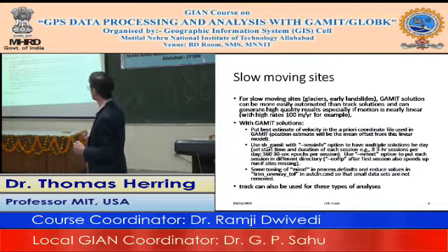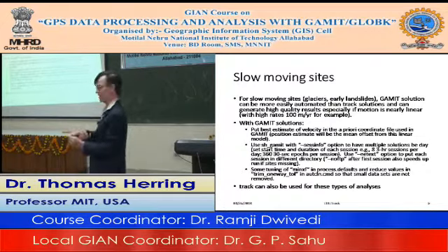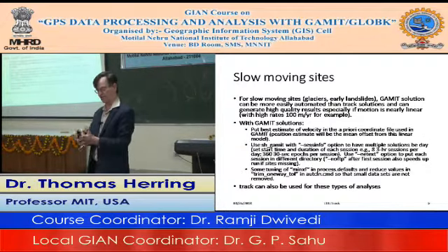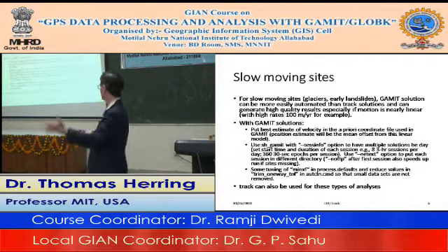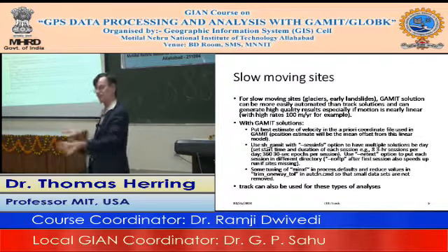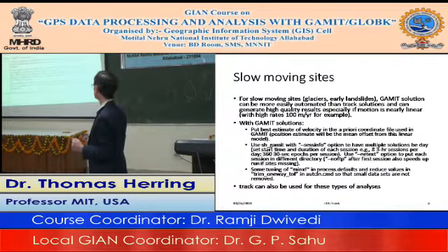So when you do it in sh_gamit, I was talking to some people about this, there's the -sessinfo option. That allows you to specify when the session starts and how long it is. So it's very easy then to batch up data to process, say, 6 sessions per day, each 4 hours long, and you just do the successive runs as you go through. You do the first one, and then we typically use the -noftp option, because once the first segment of the day is done, everything it needs has been downloaded. And you sometimes need some tuning.